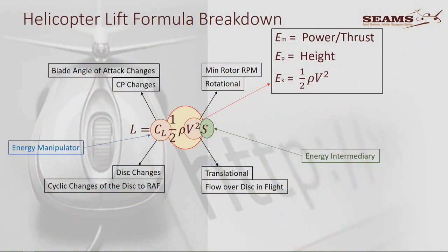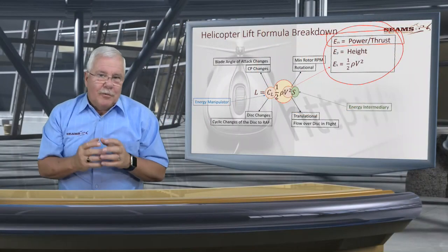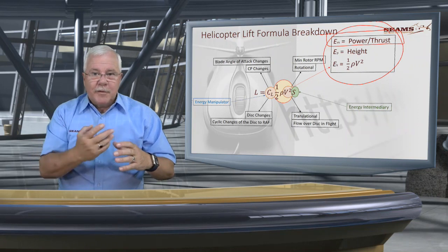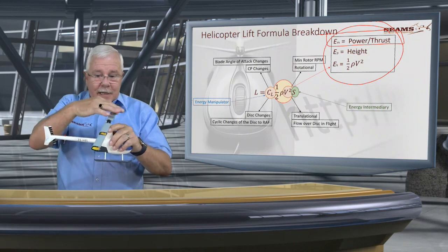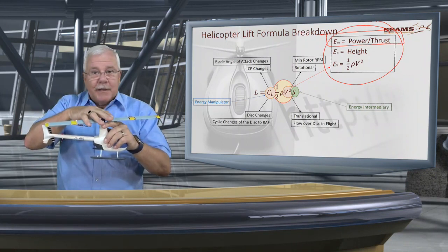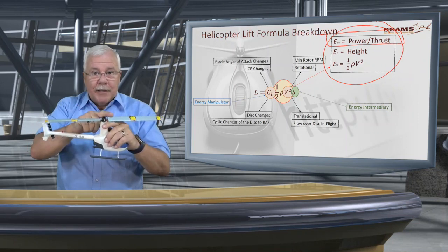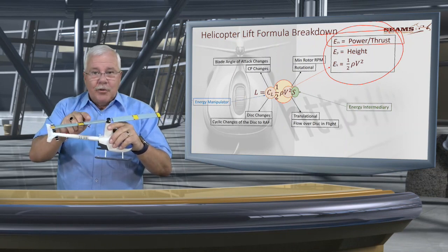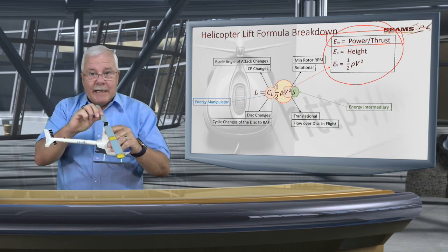Then helicopter, if we carry on here, what I've brought in now is the energies at play. Now I've already mentioned the power, so that is power or thrust. You can even call it lift if you wish, but remember the power must first start swinging the blades. Then once it has sped up to the speed that you wanted and you increase the angle of attack, the moment that you start doing that, there's definitely a huge increase in drag and more power will have to be put in to maintain this.